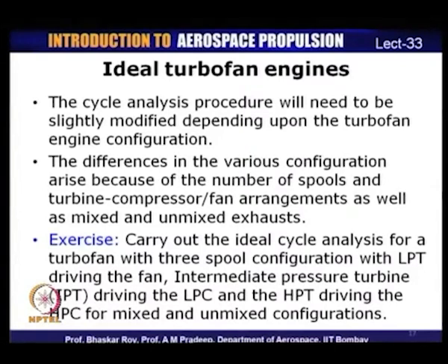spools, that is, a 3-spool configuration with the low pressure turbine driving the fan, an intermediate pressure turbine driving the LPC and the high pressure turbine driving the HPC, and you could have 2 types of configurations, either mixed or unmixed configurations. So, I leave it as an exercise for you to carry out a cycle analysis for these 2 cases. There are 2 cases here, that is, it is a 3-spool engine and one configuration is a mixed turbofan, the other is an unmixed turbofan. So, based on the discussion we had, you should be able to now carry out the cycle analysis for these 2 configurations of a turbofan engine.